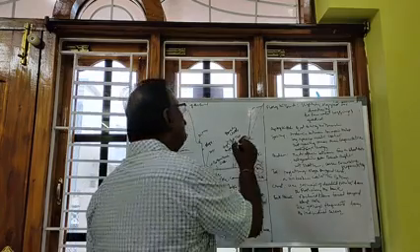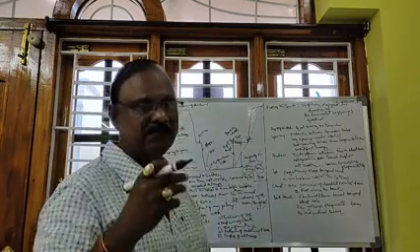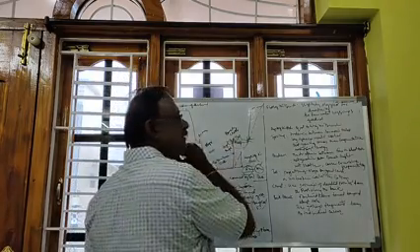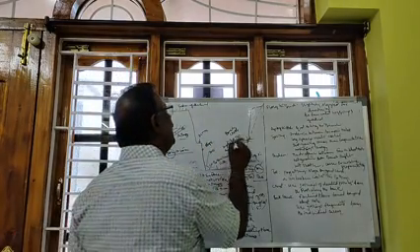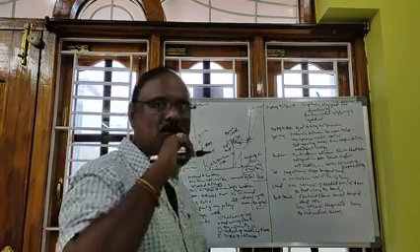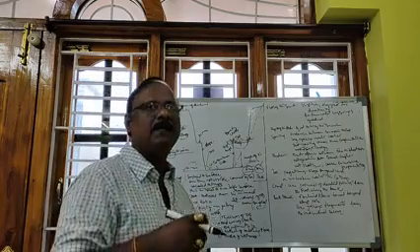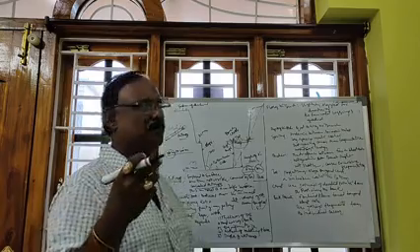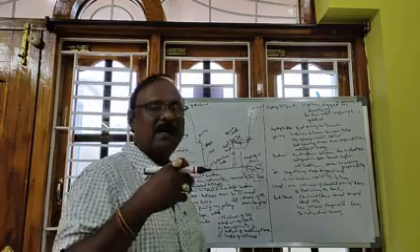So they are moving on the bench. Hundreds of tons of weight is moving on the bench. So the bench must be very stable, and for stability the width of the bench must be more than the height of the bench. Suppose the height of the bench is 10 meters, then the width must be more than 10 meters, maybe 15 meters, because of the different types of high capacity shovels, and different dumpers,